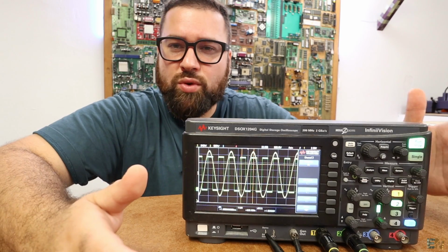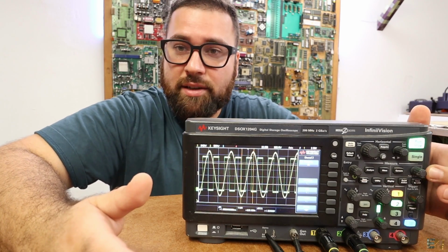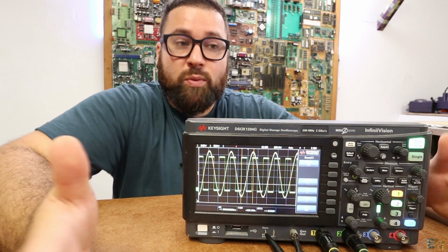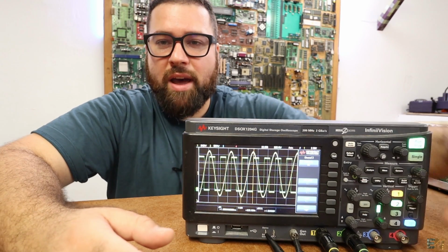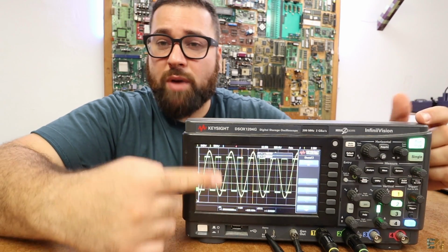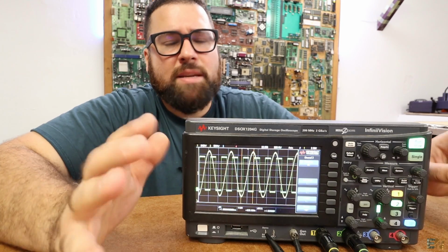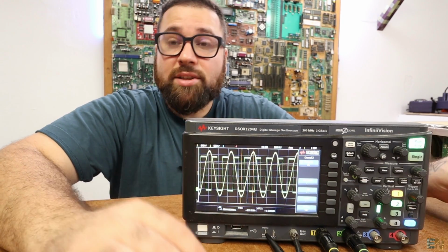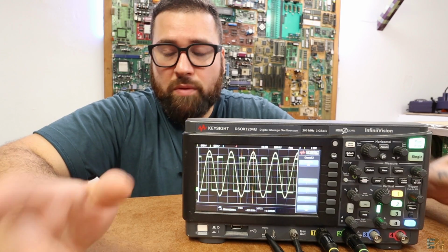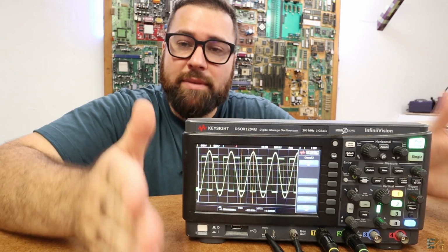Then you also know how to use the calculation, the math button and the cursor to make measurements. But once you have the measurements, you have to use those signals. Let's say that we now have connected channel 1 and 2. As you can see, we have two graphs here. But let's just imagine that with one channel we are measuring the voltage from a power supply, and the other channel is connected to a probe for current, so we are measuring the current at the same time.